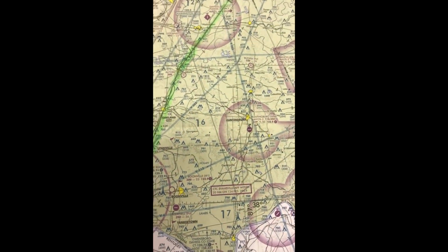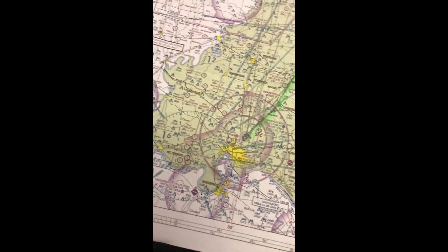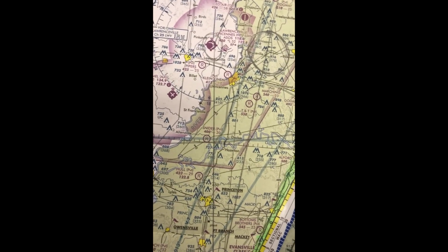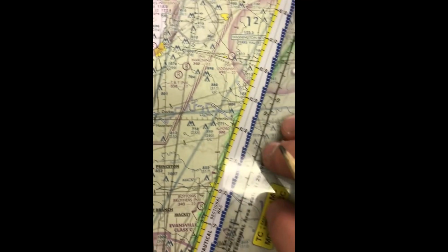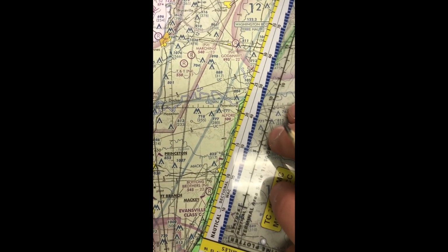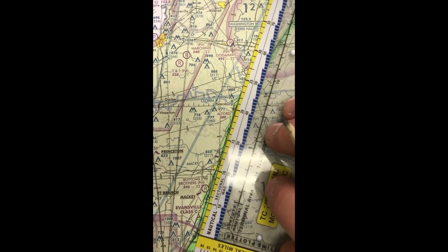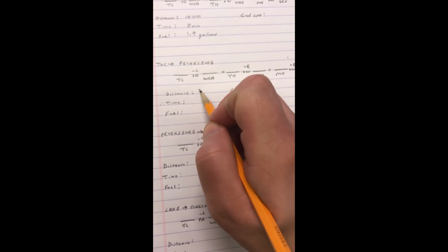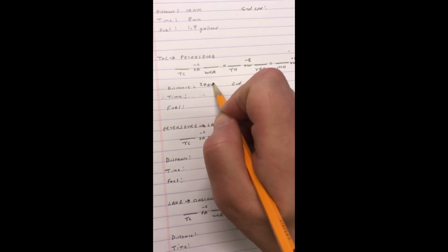So now we just need to break it down step by step, get the true course and the distance with a plotter, and then start running through the calculations. We do these leg by leg. For top of climb to Petersburg, we lay our plotter across, again making sure we're looking at the correct ones. This one works out to basically right at 20 nautical miles. I went ahead and broke down all of our equations so far with individual course calculations. So we got our distance for that first leg, top of climb to Petersburg.